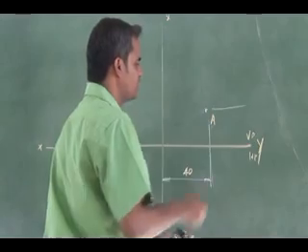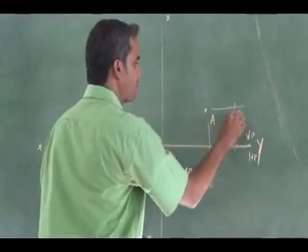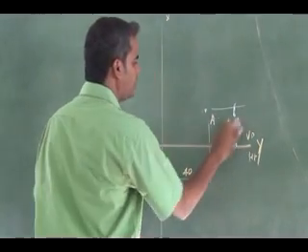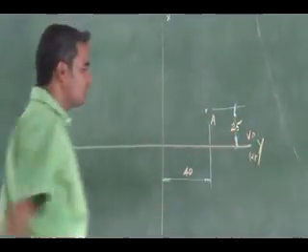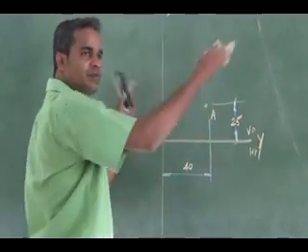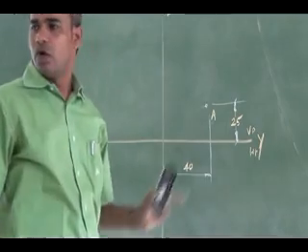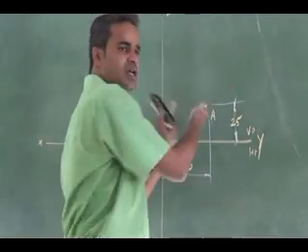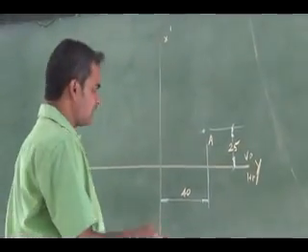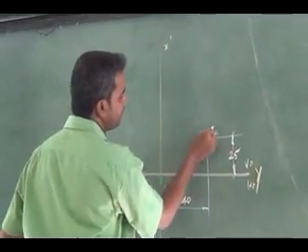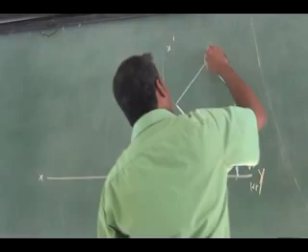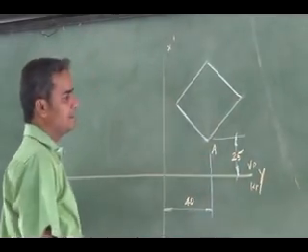This distance, the above distance, is 25. Right. So from here I can draw a true shape of the square plane. The adjacent side to this corner is equally inclined, 45 degrees, so I can draw a 45 degree line. So this is my end A.